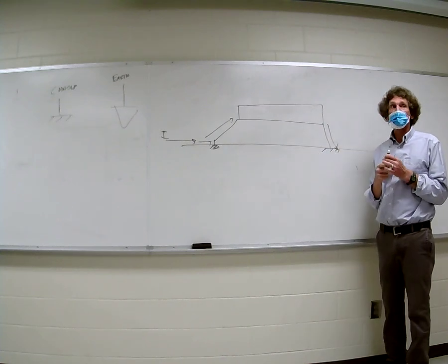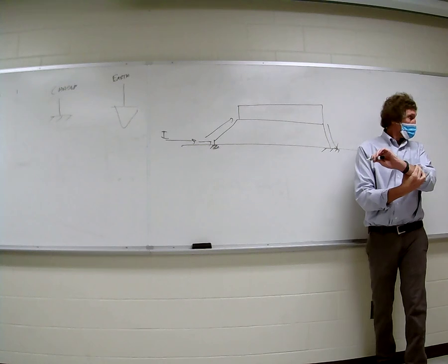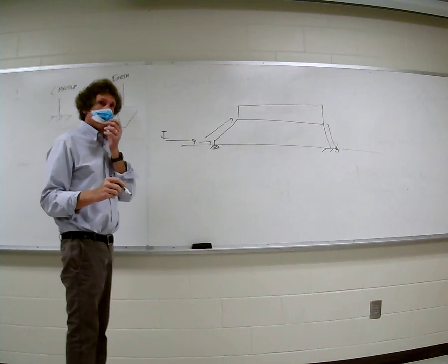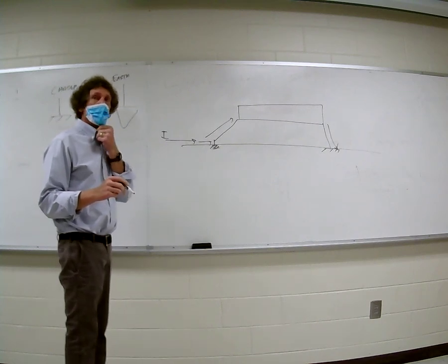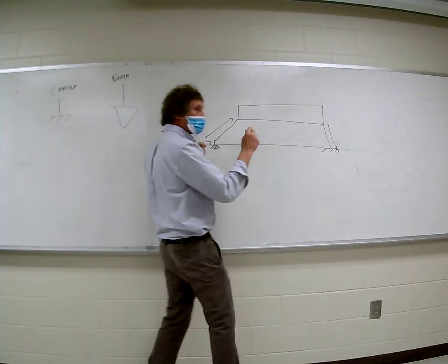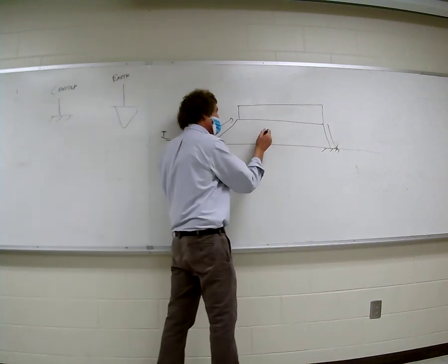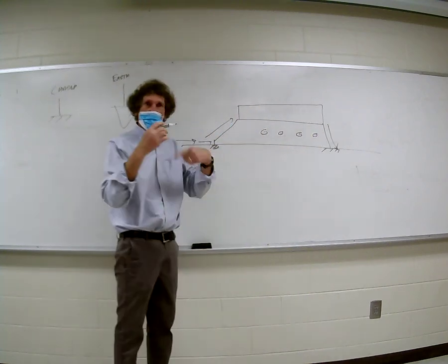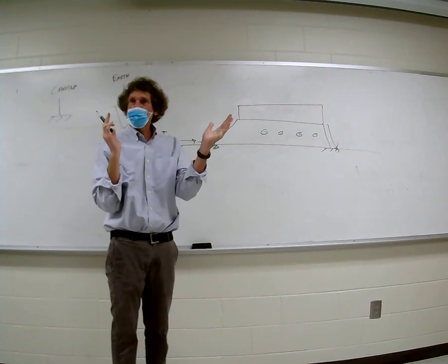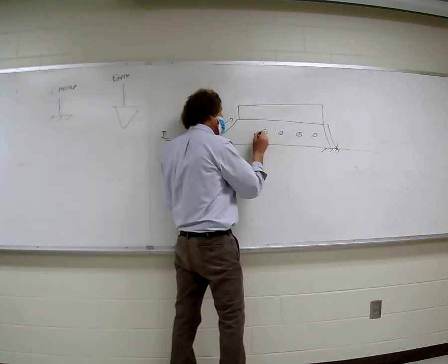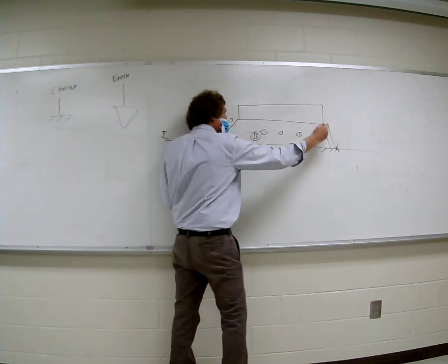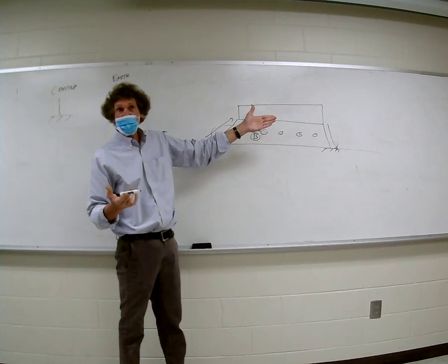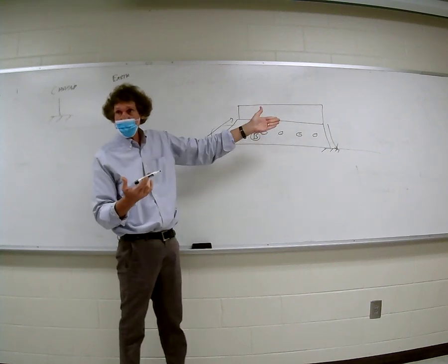Here's another thing that happens, and this is far more trouble. And this is important. Suppose I have a magnetic field caused by, say, a generator, anything with a lot of current, elevator motors, they draw a lot of current, and there's a time-varying magnetic field. Well, if there's a B field penetrating that, just look, here's a loop, isn't there, class? You know the integral of B dot ds is the flux, and the time rate of change of the flux would be the induced voltage. Y'all follow me on this?